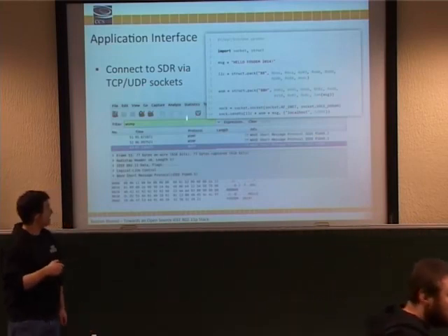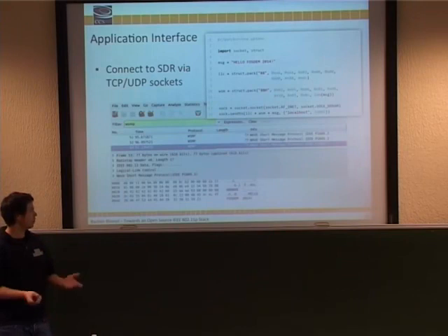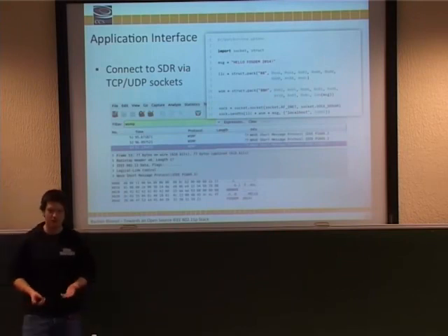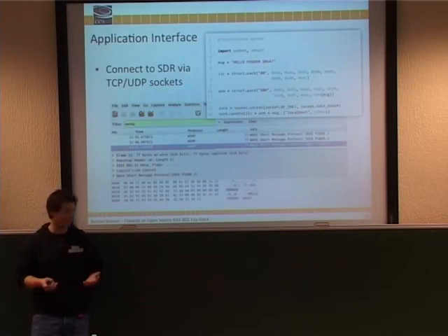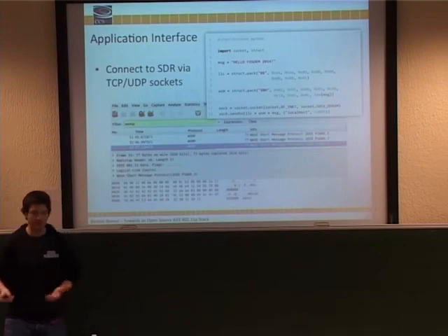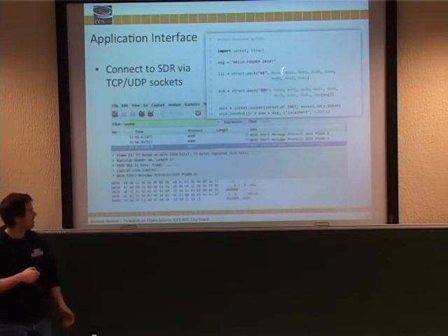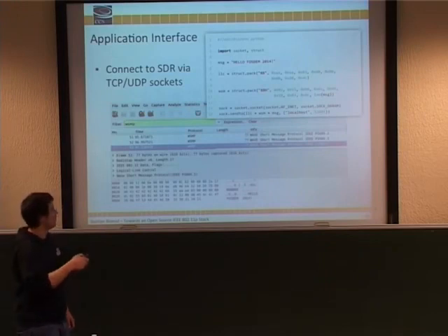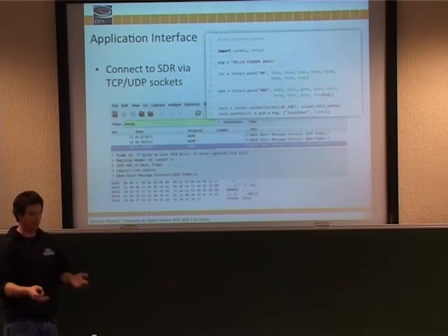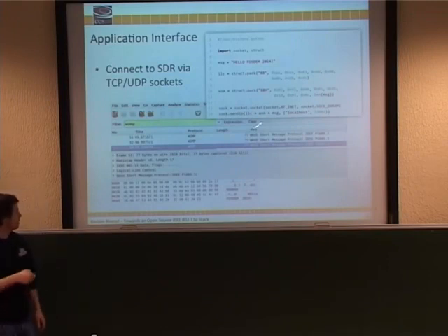In that example, I used the Wave Short Message Protocol, which is a protocol format standardized by IEEE, and maybe this way traffic information or also safety messages might be distributed in vehicular networks. You can generate those frames and maybe distribute your own traffic information, I don't know, whatever. Really easily, with just writing to the socket, and GNU Radio will pick that up and send out the frame. And yeah, we tried this with quite some hardware.